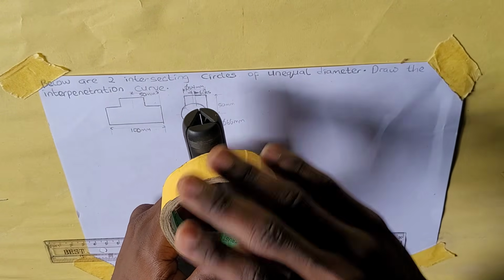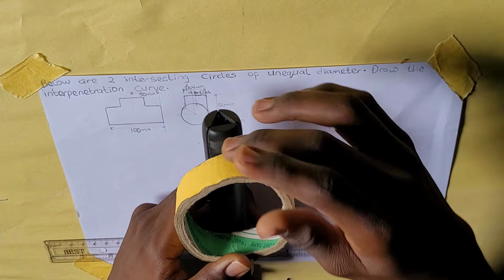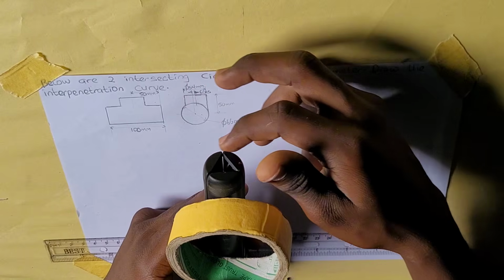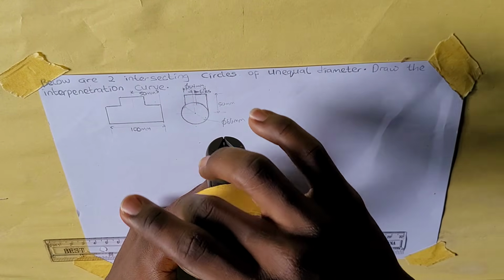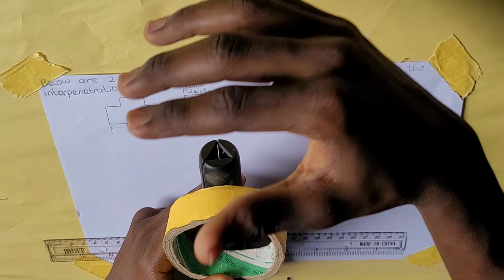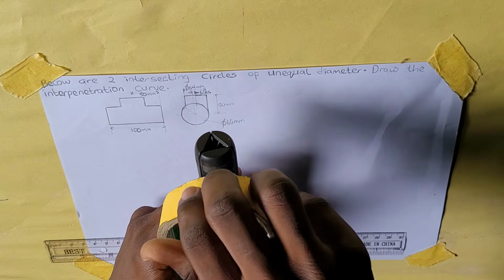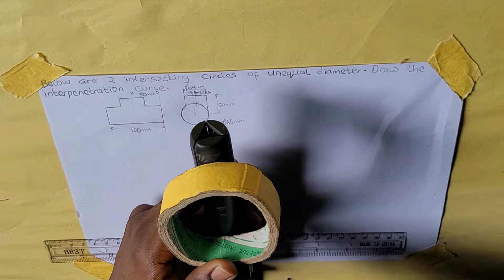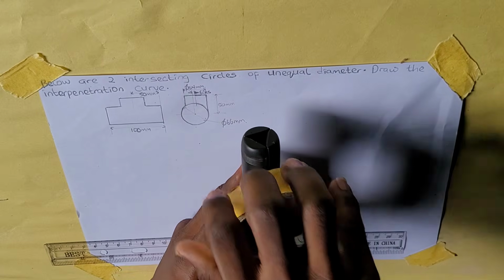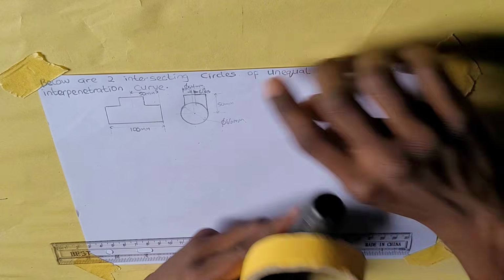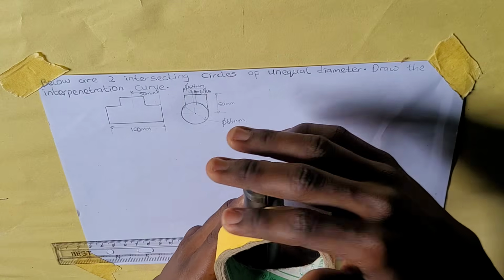If we are looking at it orthographically, like in orthographic projection, from this side, this is our side view. This side looks like a circle, which is what we have here. And then on top, we have this curved part, but because we're looking at it directly, it's going to look like a square. We can only see this part of the cylinder. We cannot see anywhere behind. So this cylinder on top, this part that we can see here, is this thing that looks like a square on top of this circle.